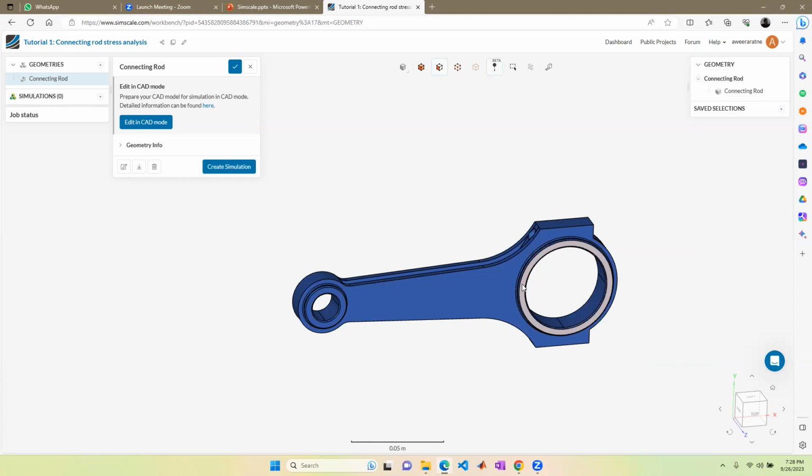If you rely on your basic mechanics of materials knowledge, you should be able to intuitively figure out that this area will undergo some extension and this area will undergo some compression. And as a result of that, points at the extreme ends will undergo a large displacement.